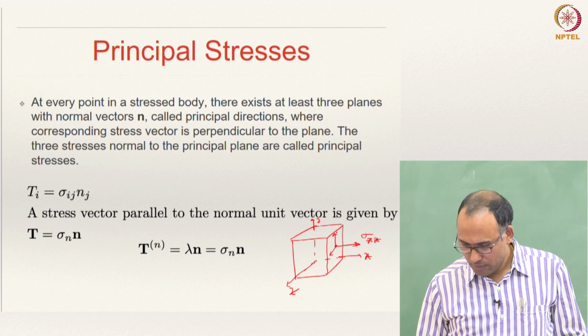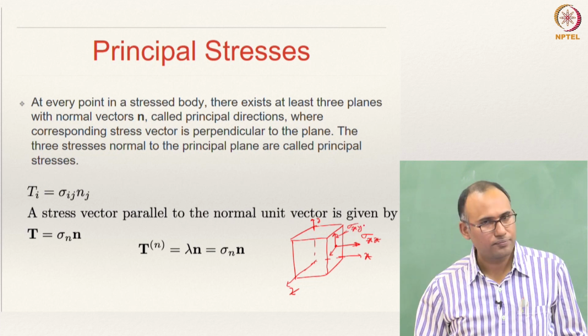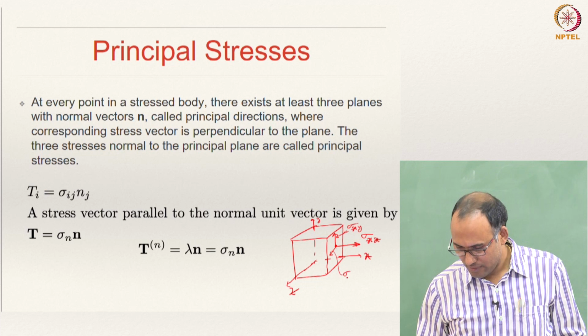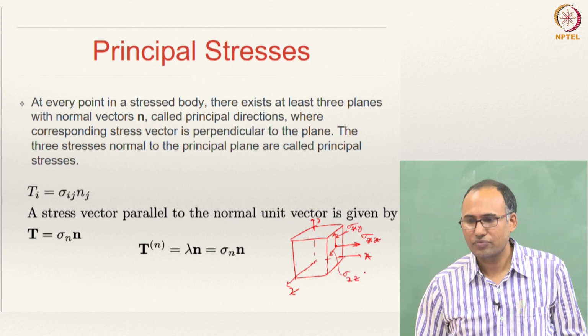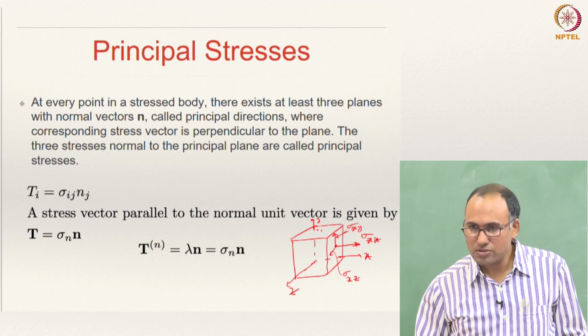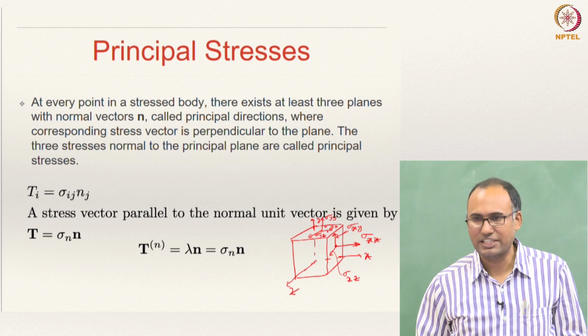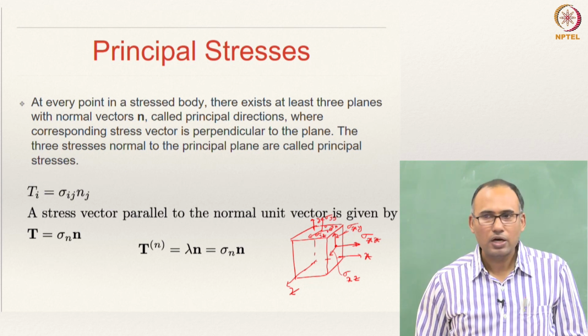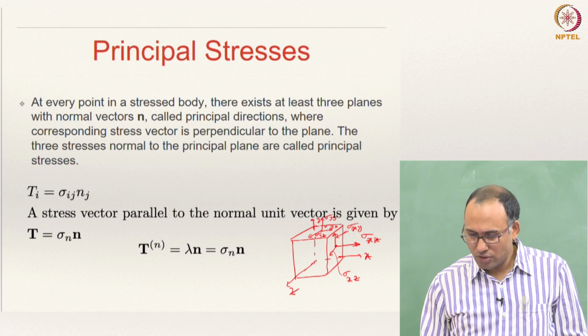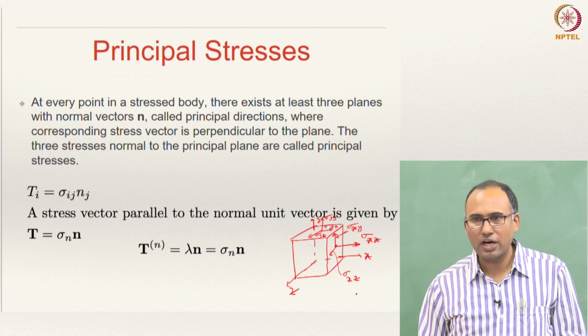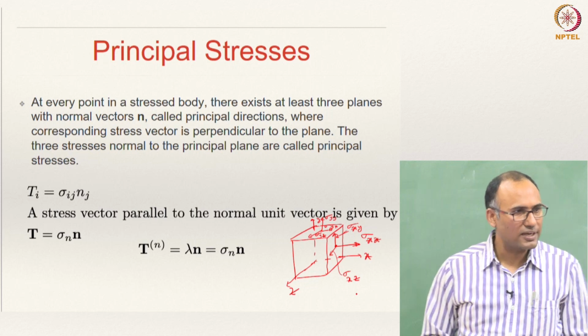And this I am calling sigma xy, and this I am calling sigma xz. Similarly, on this plane you have one normal stress, that is sigma yy, and that will be sigma yx, and that will be sigma yz. Like that you can show your stress state on all the faces, right.